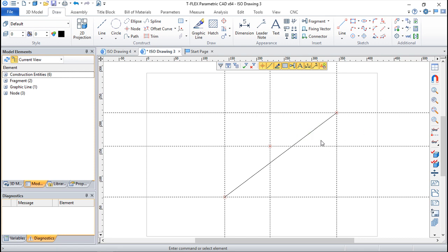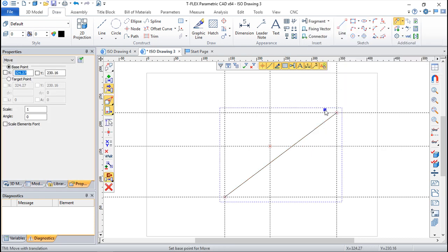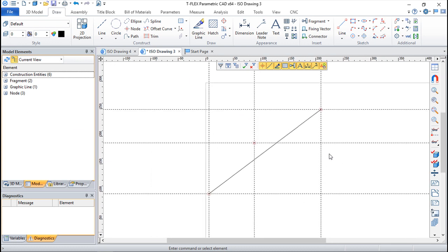But I can also choose and pick some entity, and after choosing the entity, I can change something around here, or simply coming to this menu that appears and say, for example, move with translation. Okay, one point to other point, and I'm moving. So it is what we call the transformation only with the clipboards, without going to icons.